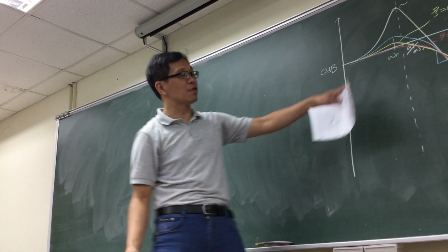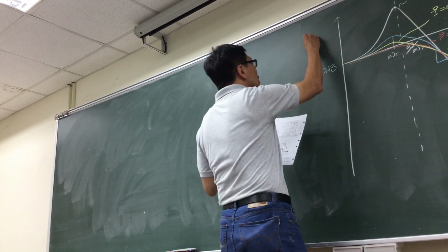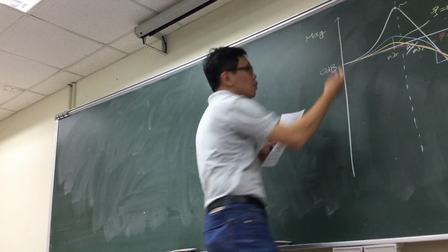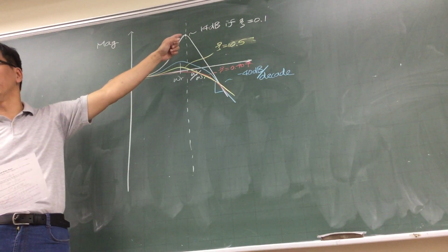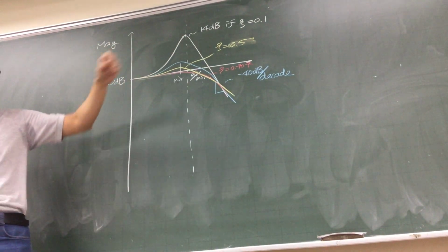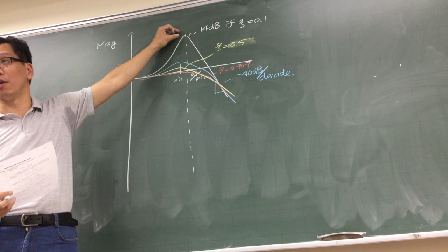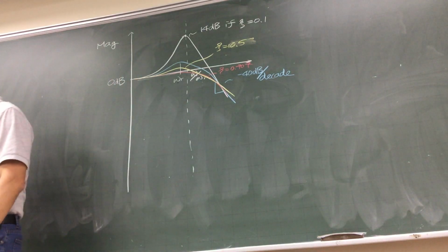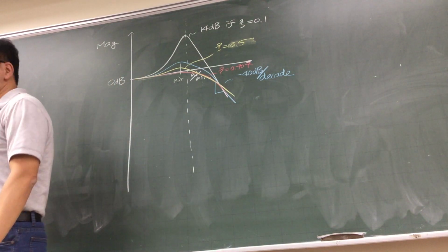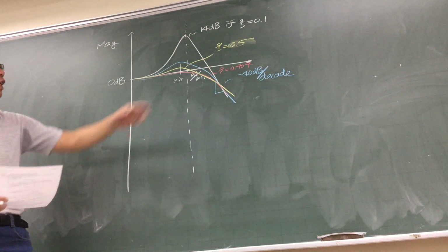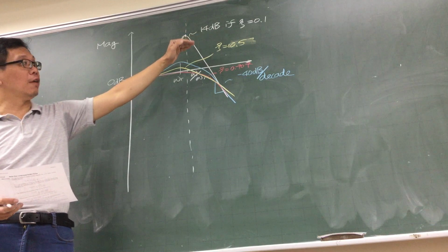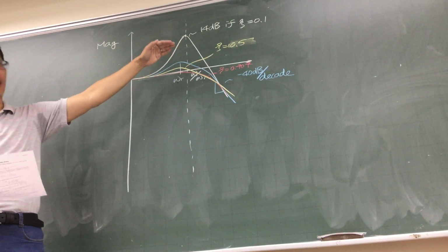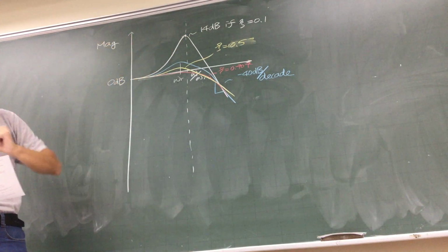There is another part. This is the magnitude part. Few things you need to remember. The first thing is how are you going to identify the peak over here? Depending on your damping ratio, you're going to identify how tall this one is going to be based on the equation I just erased over here. You should be able to find out if your damping ratio equals 0.1, how much dB we're talking about. If it's 0.2, how much we're going to talk about, and those kind of stuff.